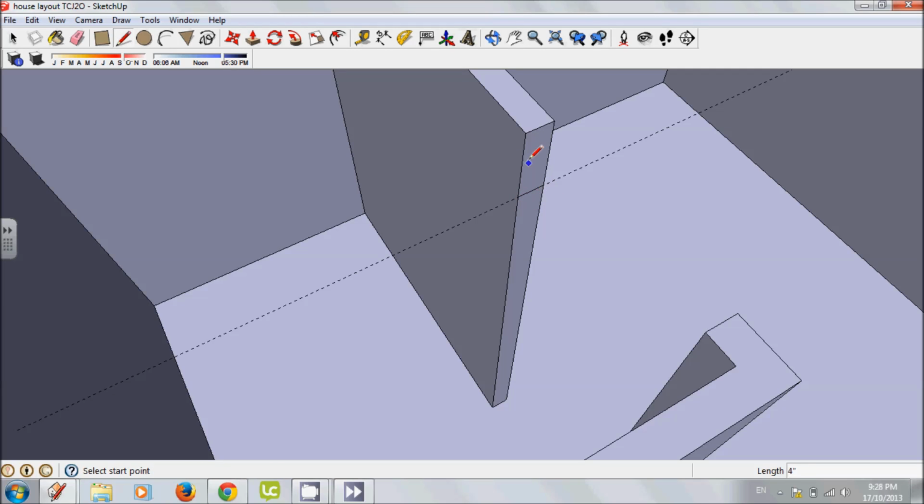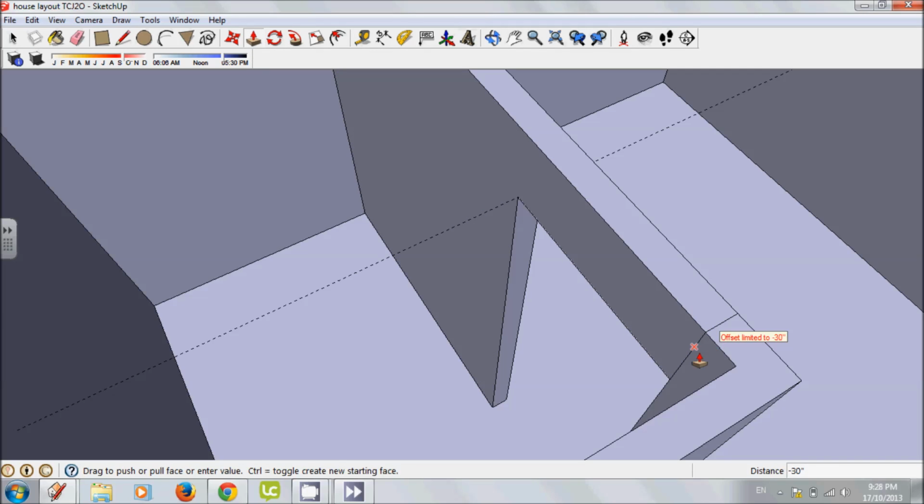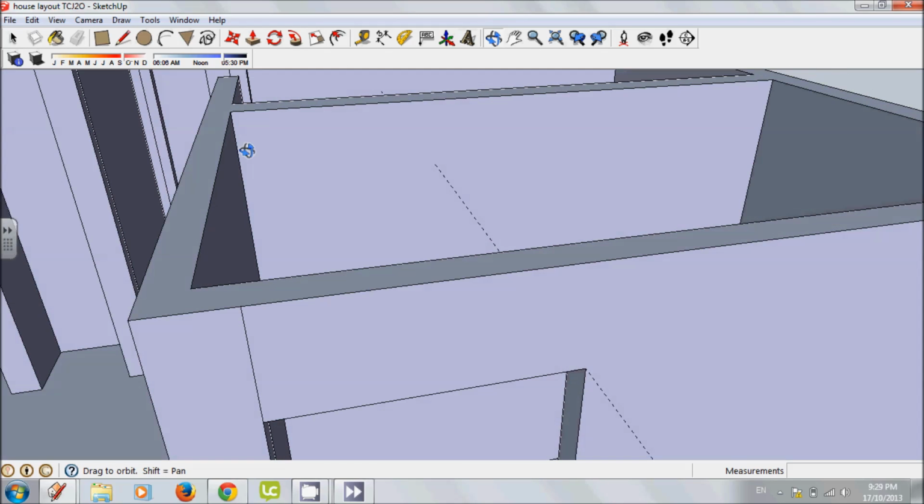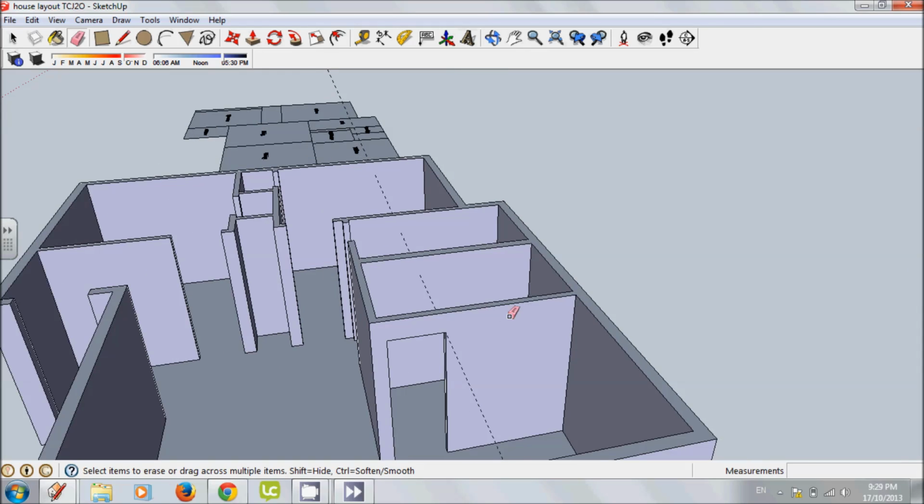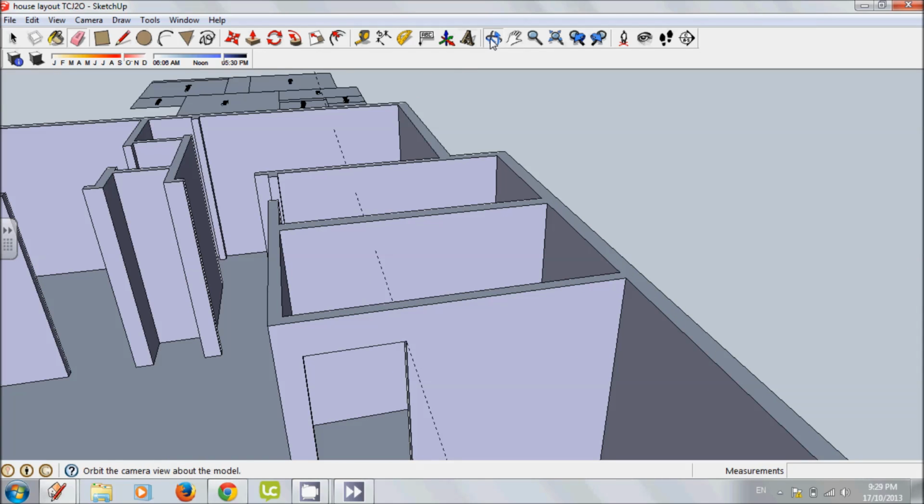from the ceiling. Which means that if we took a tape measure and measured from the floor up to this line, it should be 84 inches or 7 feet. So we've produced this line across here. All we have to do is grab this push-pull tool, pull this across, and it will offset the limit to the width of the door. And then while you're here, you may as well just erase these 2 lines and the line on the other side, and then you've got a nice clean wall you can work with, and you've got your header in place.